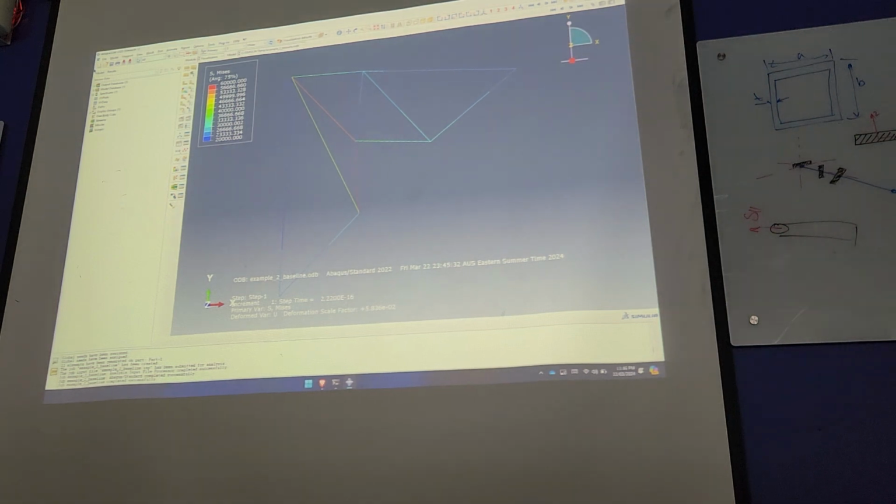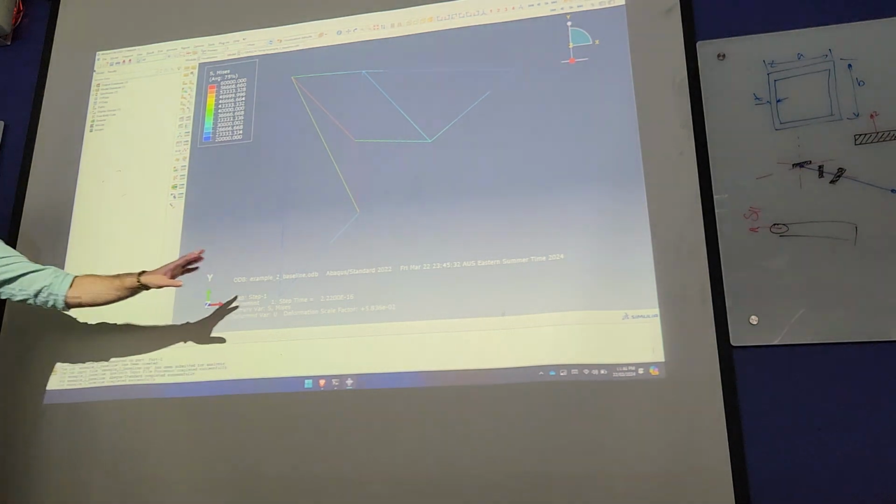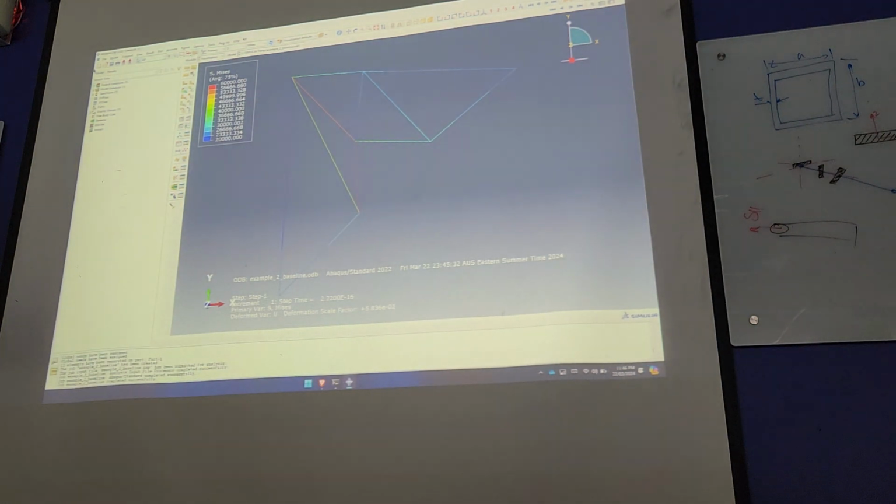Okay, so here's the thing. I just put some random values in. There are small profiles, all the same, and to see what's happening there. And we got stresses that are ridiculous. They are in 60 gigapascals. So obviously it's too small. Everything is on. But that's good for now.